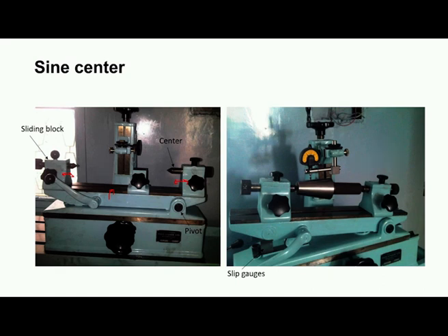To accommodate workpieces of different lengths, these two can be slid. You can see here the taper component is mounted between centers, and then there is an attachment here, an arrangement for mounting the dial indicator.